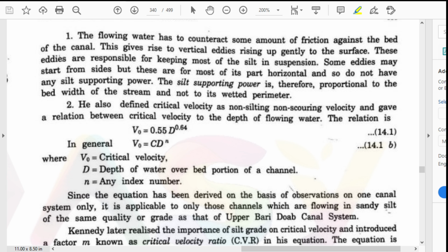Okay, as we decrease the velocity, finally the discharge will decrease. And again the irrigable area of that particular canal will decrease. So we have to remember some points while designing any canal system, that is an alluvial canal system or a non-alluvial canal system. Okay, now here.